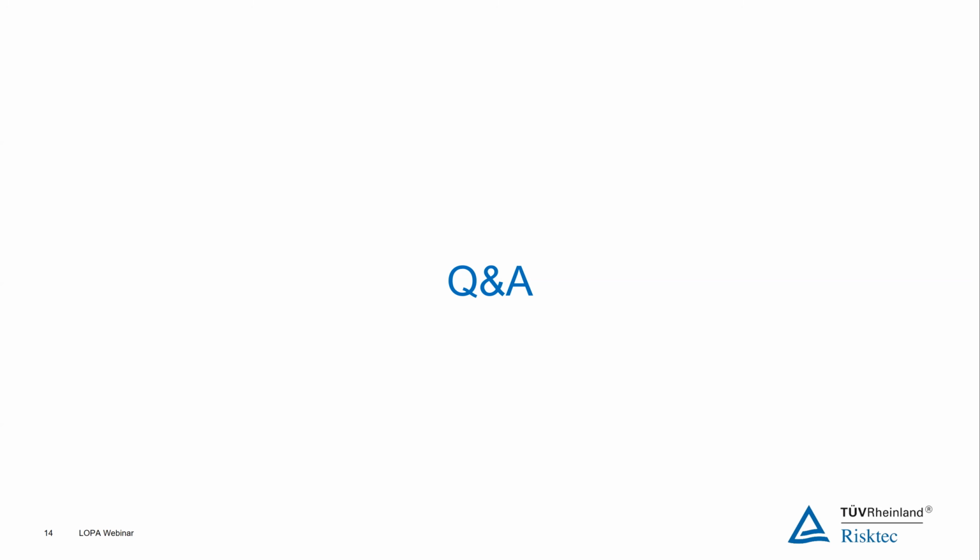Yeah, sure. Just quickly, yeah. So I think you could consider PHA and HAZOP are both going to be your hazard identification exercises, where you run through your process systems to assess what are the potential causes of safety or operability issues, what are the consequences of that, and what safeguards I have in place.